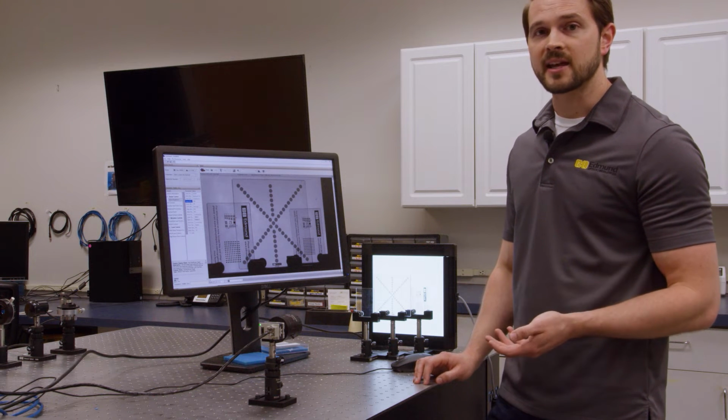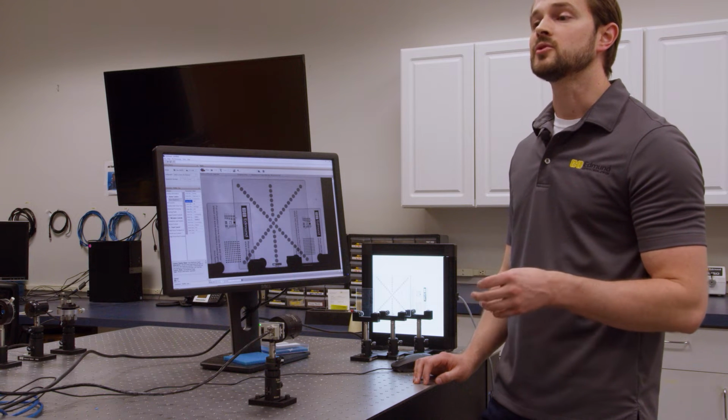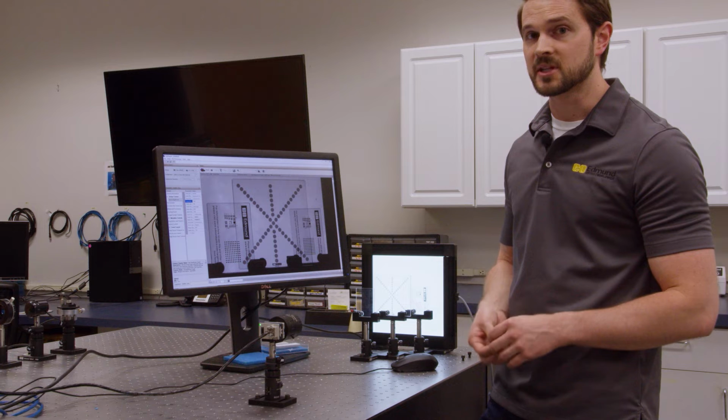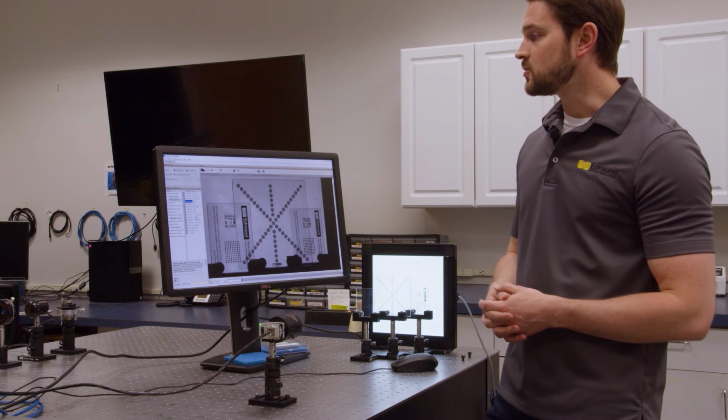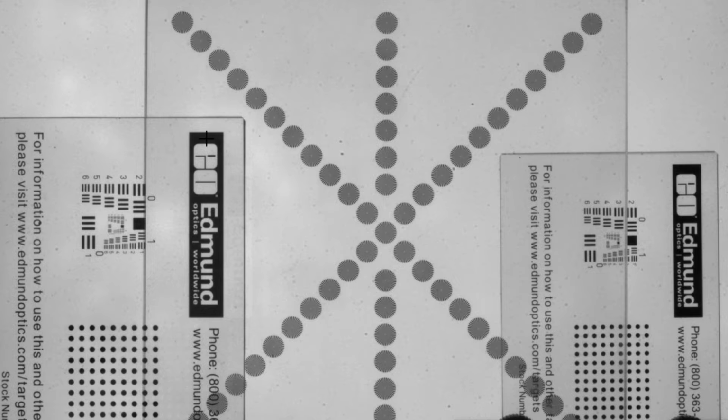And once you go beyond that, you're no longer taking advantage of the small pixels and you're no longer able to resolve down to that particular feature size. So that can have a huge impact in what you're actually trying to view. In this particular case, if you're just trying to look at something that's, say, the size of this EO here, you would be just fine running at f16, especially if you need to see it over a large range. The important takeaway here is that you cannot continue to increase your f number just to buy more depth of field, because you will very quickly start to lose resolution performance.